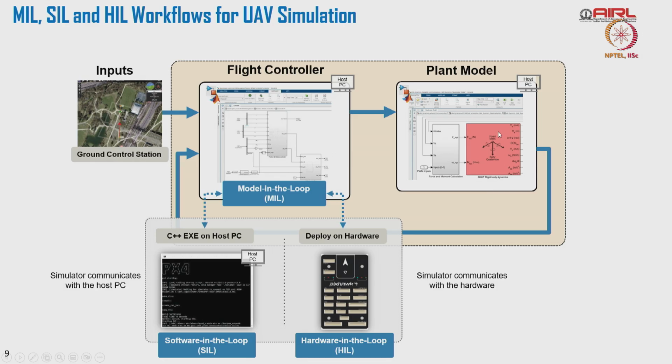The states of the system, you have sensor models also here, right? Whatever the sensor model gives, I have to pass that to my Pixhawk, where I do a state estimation. Using the estimated state, I do the control calculation. Finally, I'll tell you what is the RPM I need from all, let's say if it's a quadcopter, all four motors, or if it's 6 or 8, depending. I have to give all the RPM and thrust requirement, torque and thrust requirement, and again that needs to be converted, right?